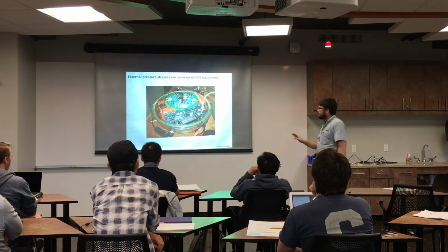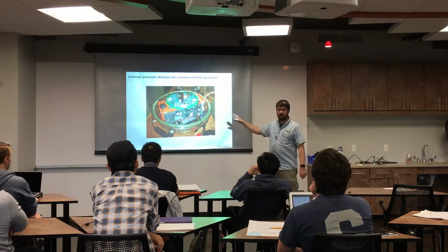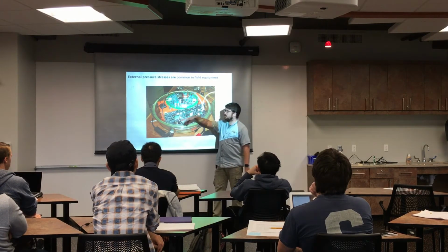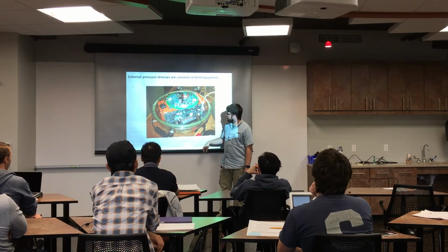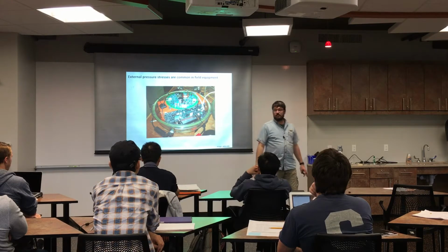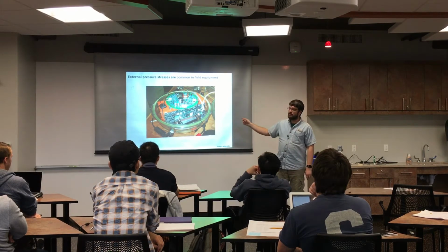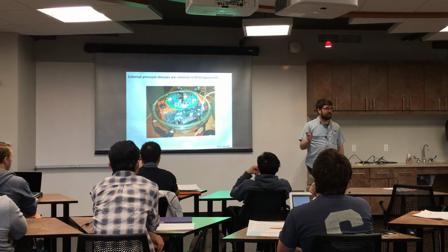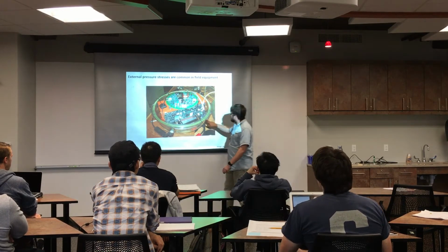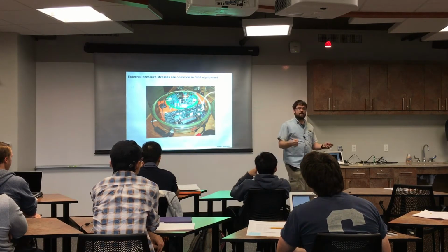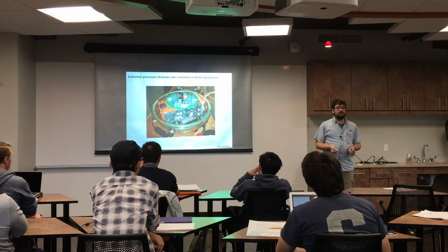This is the guts of an ocean bottom seismometer up at Woods Hole. And so they've got all kinds of logger electronics and all this stuff in here. There's a battery down there. What it is encased in, and these go down to thousands of meters depth, is a solid glass sphere, just like windshield glass. But it's very thick, it's precision ground, and then these two precision ground glass surfaces mate together and they clamp it. And that's good to thousands of meters of water depth.